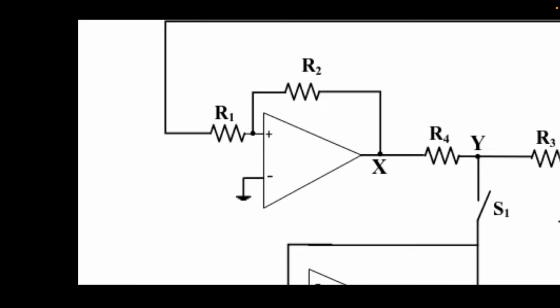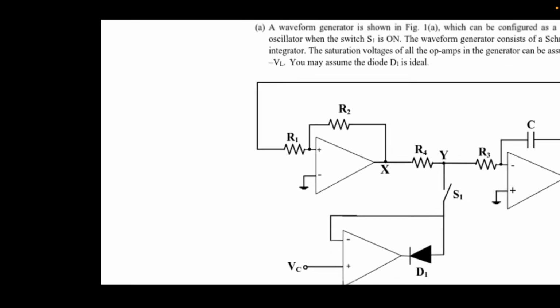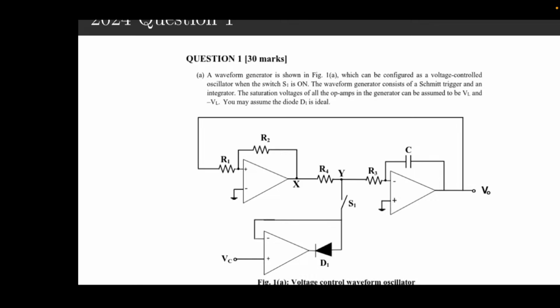Why is that? Because the difference across the two terminals is positive. Pretty simple. And if you have a negative voltage here, then it'll saturate down to negative VCC. Okay. So that's the foundation for how we're going to do these questions, nonlinear amplifiers.